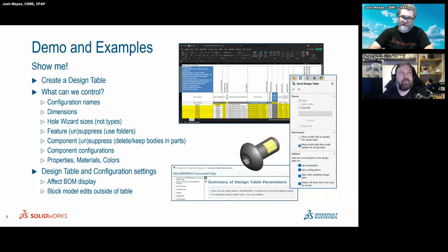When I was talking about doing configurations for my 3D printed parts, sometimes we want to show in the drawing an overlay of the as-built part and the end item part. So oftentimes with metal 3D printing, there's some finish machining that has to be done. You could imagine the same thing with a casting and a machining. There's usually some finish machining done to a casting to make it a final part, an end item part.